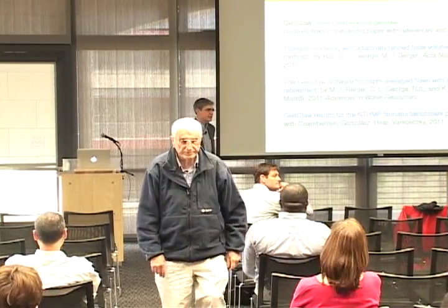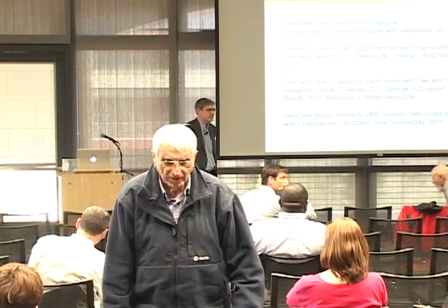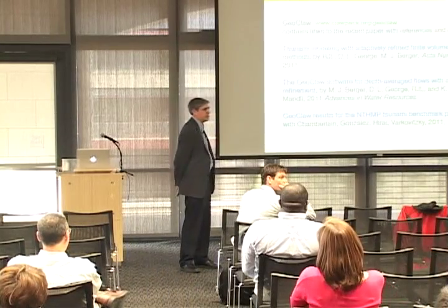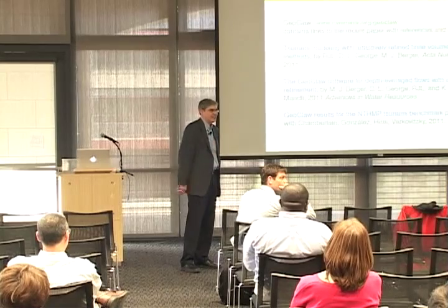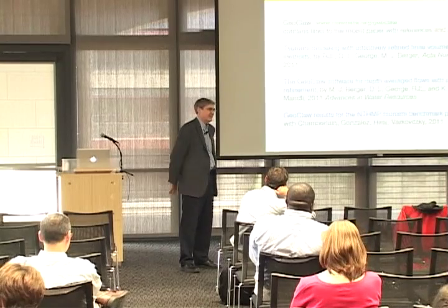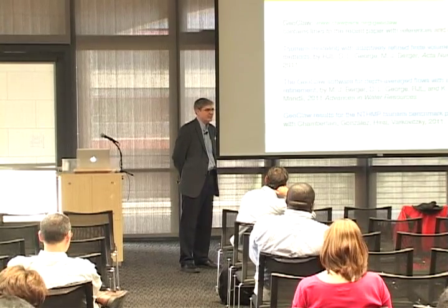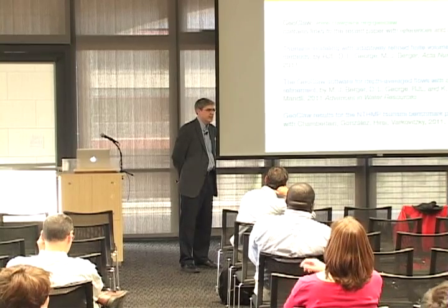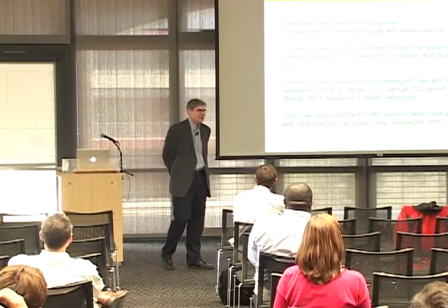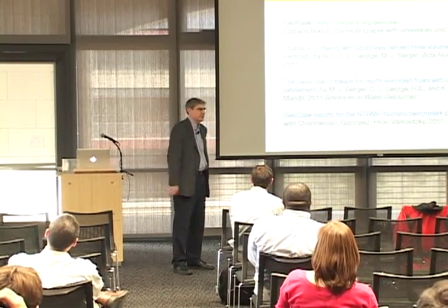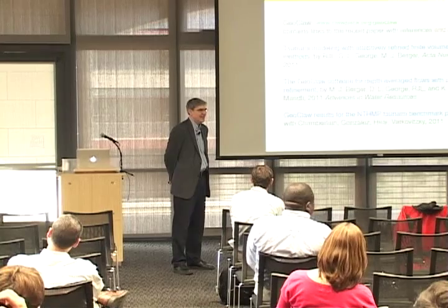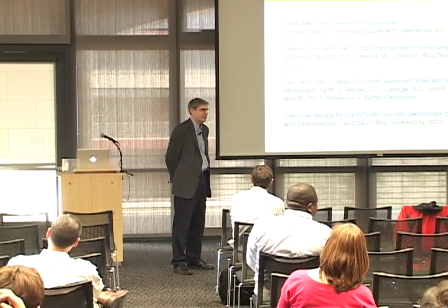In terms of sea level rise, if sea level goes up substantially, then the tsunami mapping would presumably have to be redone at the higher sea level. When we talk about something like a 100-year flood, that has to be interpreted as a 1% probability of occurrence in the next year, valid with the current level of sea level. And if sea level changes significantly, then things would have to be redone. But when we're looking at these big events like a Cascadia subduction zone magnitude 9, which is 10 meters of water coming in, a few centimeters of rise obviously isn't going to make any difference. So it depends on the scale of the event you're looking at and how much sea level rise we're having.